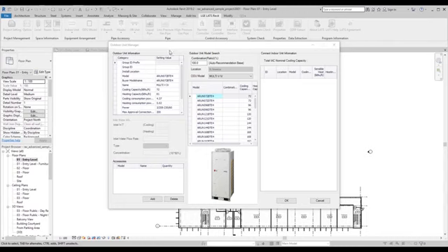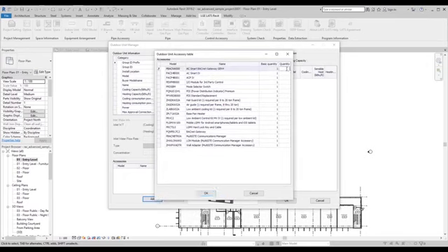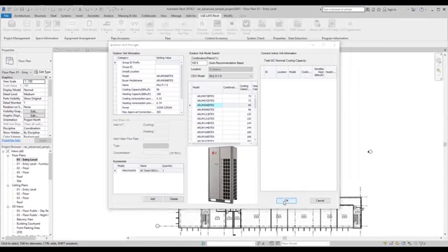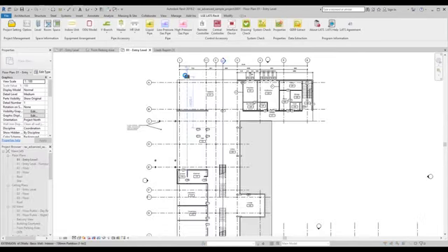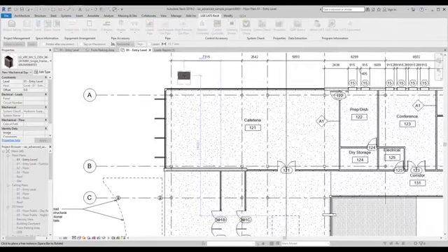To insert an outdoor unit, click Outdoor and choose an ODU model. For now, we will use this Multi-V5 model. We may have to come back and change the size of the unit, depending on the indoor units we add. You can add accessories to your outdoor unit and place it in the plan. The red box represents the recommended clearance for the ODU.